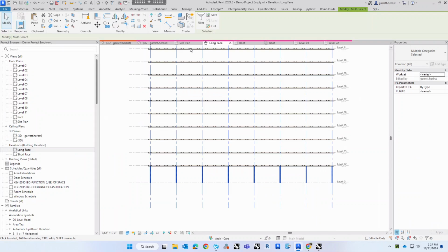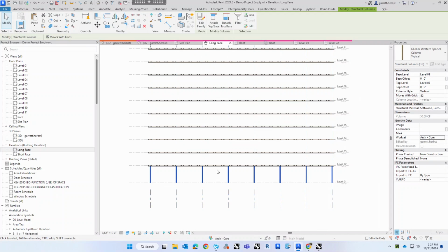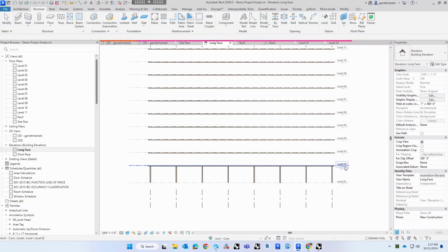And that's one of the nice things about doing it out of Revit elements and not just trying to do it in Rhino, because Revit has inherently a ton of parameters. It's a building information modeling. You are designing with all the different parameters that could be associated with a building component. So you can select all of your columns, and within the columns themselves are different parameters. Of course, you can change what level you want them to be associated with. So if you want it to go all the way up to 5, you can do that.